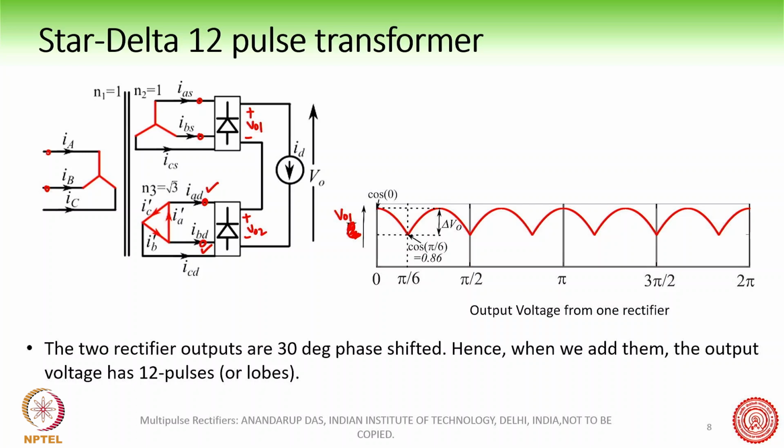So this line voltage will have either a plus 30 degree or minus 30 degree phase shift. There is a 30 degree phase shift between star and delta, and that is why we often use this kind of arrangement, YD1 or YD11. Those who know about transformer connections know that there is a phase shift of 30 degrees between the primary and the secondary here.